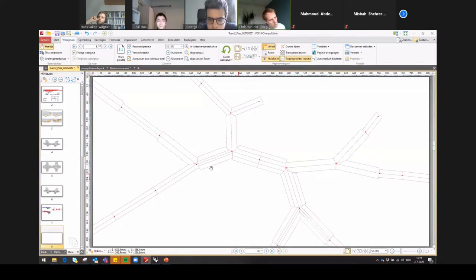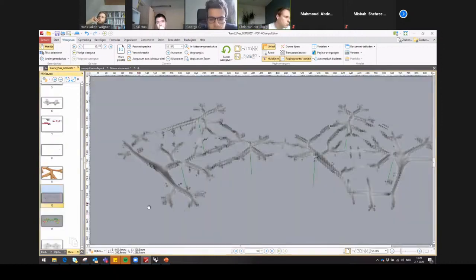The next question for us was, how can we inform this pattern with real behavior? The first step was making use of density as an approximation for how big the bending moments in certain beams are. This is the density plot you normally get. We added some additional pictures to get more of a feeling for which sections will get what density, and more red means more density, so a larger section.